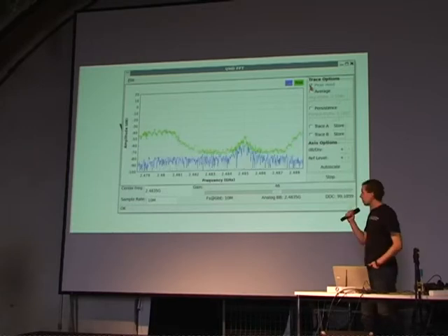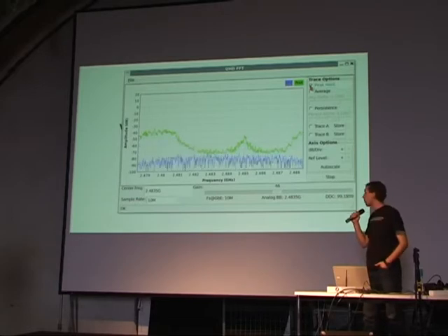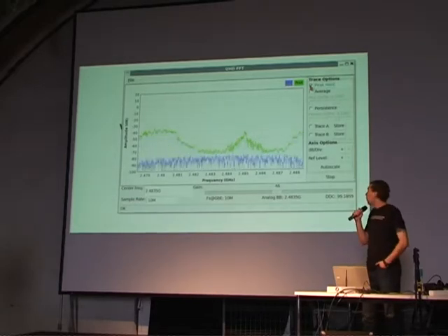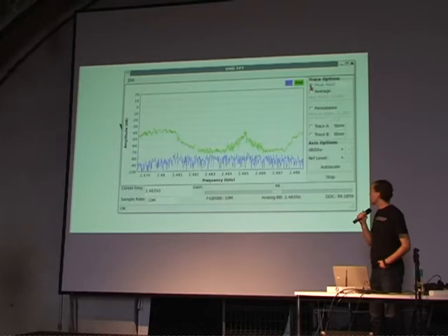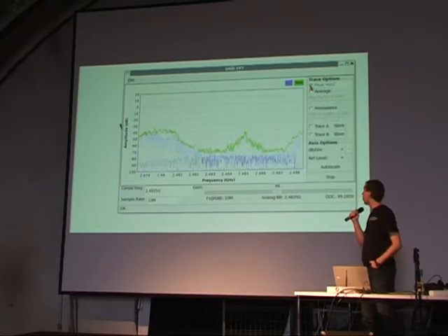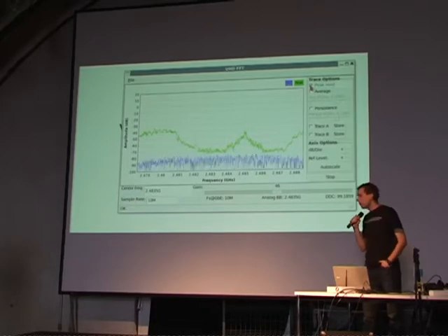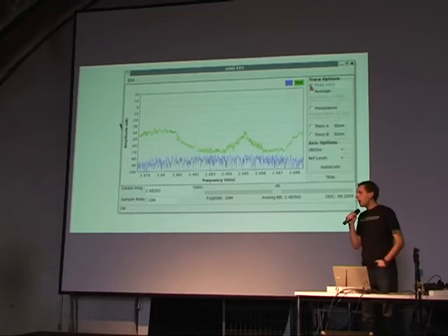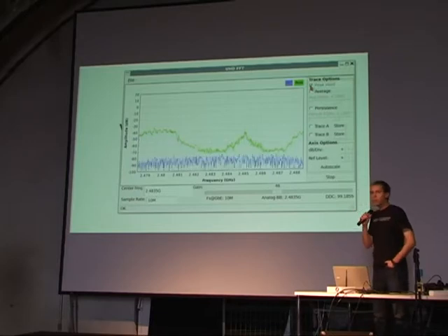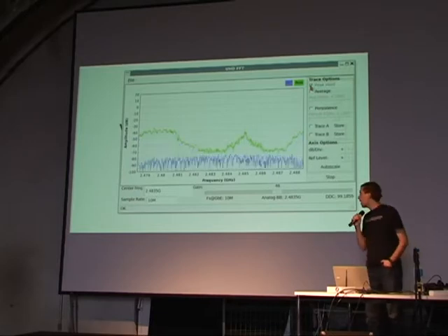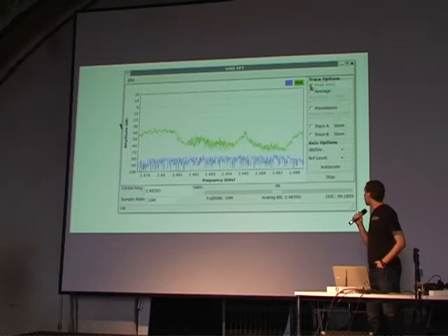What this actually does, it acts as a spectrum sensor for the communication of the mesh network that the badges are creating. Since there are too many badges here, I don't necessarily need to pull out my own badge, which I had to do at home to receive something in that spectrum. However, what we have to realize is that the badges are operating within the ISM band, which practically means that everything, be it Bluetooth or wireless LAN, can be in that spectrum.